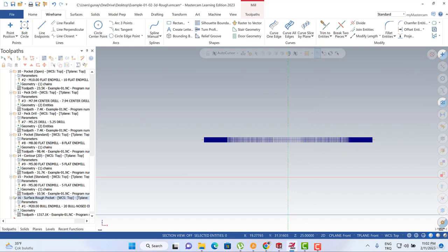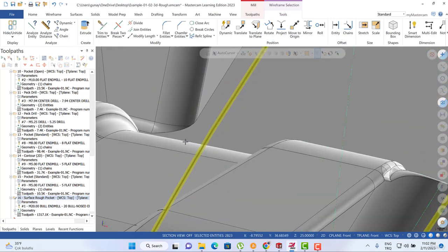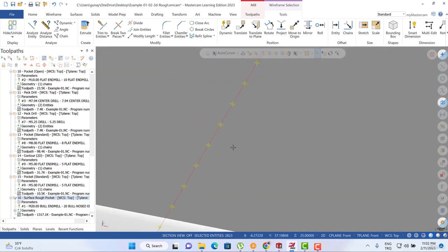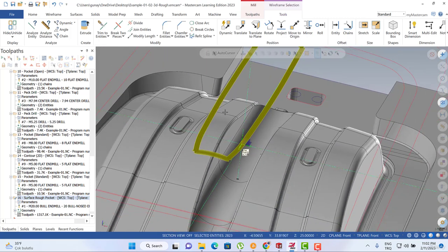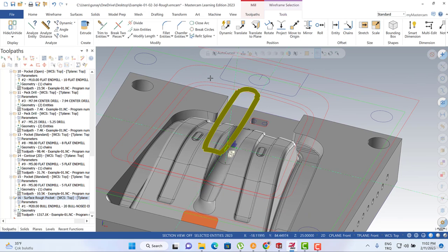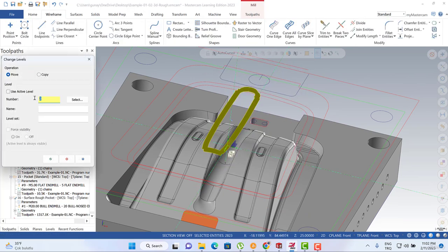You're going to focus on here. So we can select here, select the only point entities option, and then we can select here. You're going to see that all our curve is not selected. After that, we can use the right mouse button, hit the level options, and then we can send all my points to the level